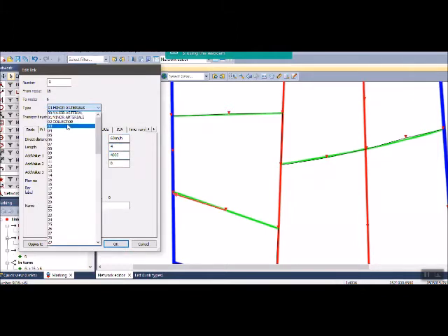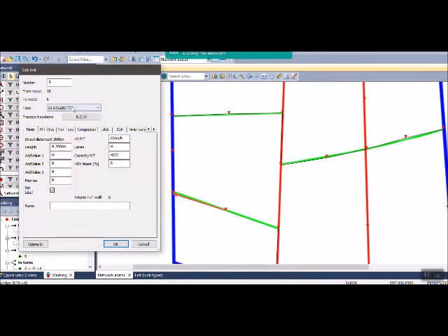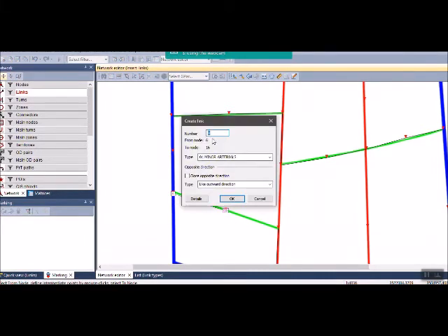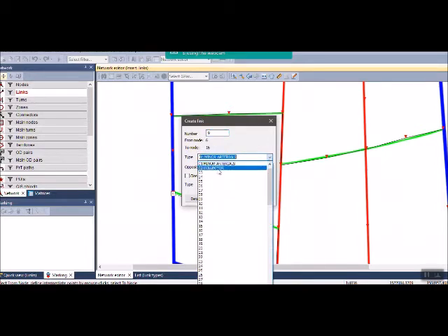But when I change it to its correct type, which is collector, these things are not modified. So I'm going to modify it manually, which is 50 km/h, the lanes are 3, and the capacity is 3,000. So it is better to delete it, because you can have something wrong in here. This is a collector again, but it's better to delete it so it is automatically assigned its characteristics. So I'm going to delete it and add it again this way, and choose it again correctly, collector.